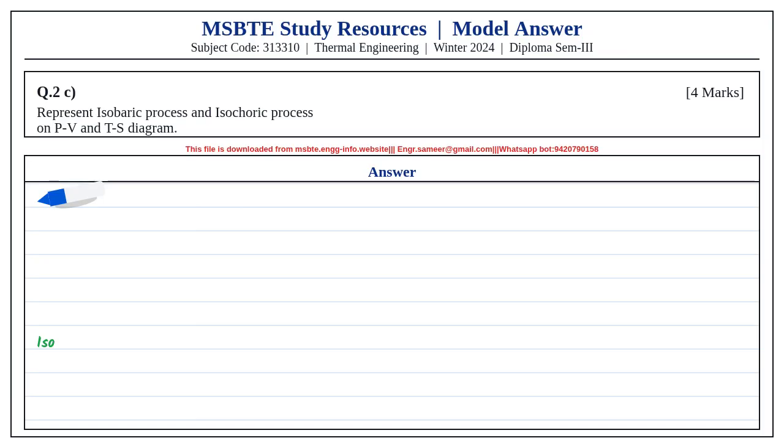From steam table at 9 bar, saturation temperature is 175.4 degrees Celsius and specific volume of dry saturated steam is 0.215 meter cube per kilogram. Since the given specific volume is greater than Vg, the steam is superheated.